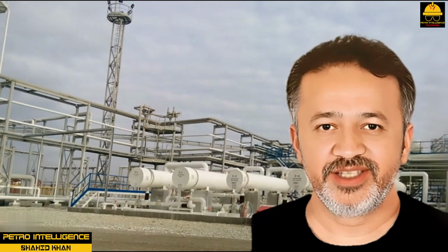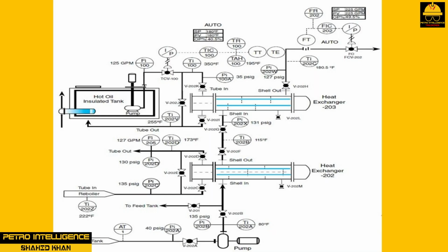Startup procedure for heat exchanger system. Prior to startup, the feed tank has been blended, sampled, and prepared for introduction into the heat transfer system for processing. 1. Notify your supervisor and all concerned about startup: downstream process technicians, I&E, engineering, maintenance, etc. 2. Ensure all safety hazards are secured: trash, locks, old permits, etc. 3. Check equipment and instrumentation, stroke control valves 0 to 100%, check lineups, etc.